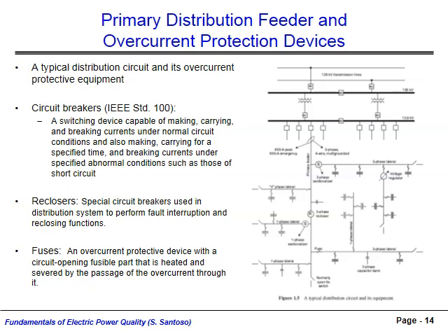When a short circuit fault occurs on the system, customers will experience voltage sags or interruptions depending on their location in the system with respect to the fault. High magnitude current will flow to the fault location, activating protective devices in an attempt to isolate the fault. While fuses can easily isolate a fault, they must be manually replaced after they have blown out, and many faults are only temporary. If the fuse blows, downstream customers will experience a sustained interruption while workers replace the fuse.